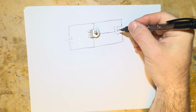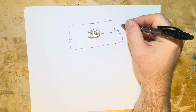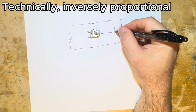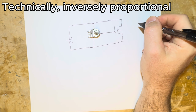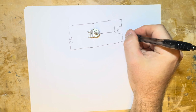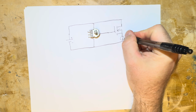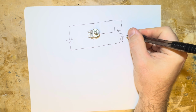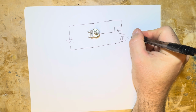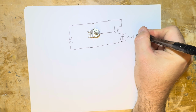So what that means is that the resistance of the MOSFET is proportional to the gate voltage. So what we could do with that is that if we put our load in here in series with this, we can target a particular voltage drop across our 0.25 amp load.